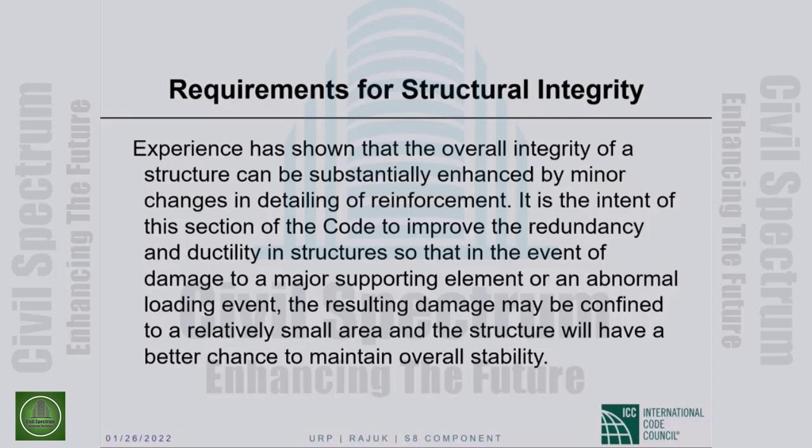BNBC, I don't know exactly where it is, but in IBC there are detailed pile detailing requirements, and some things are relaxed, like everything that applies to a column doesn't apply to a pile. But the spacing limitations, I believe, are the same. So this will be my answer unless I find something else in that chapter. I would like to check. The spacing between longitudinal bars and so forth is what I was talking about.